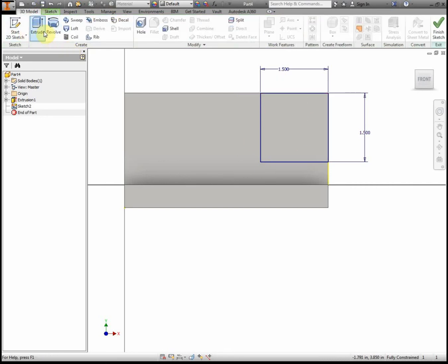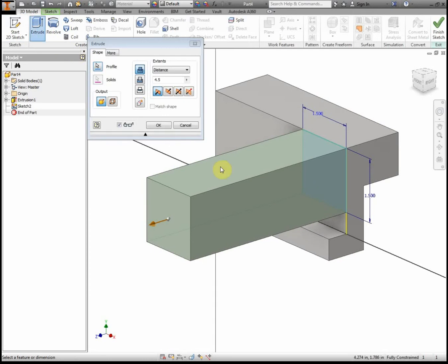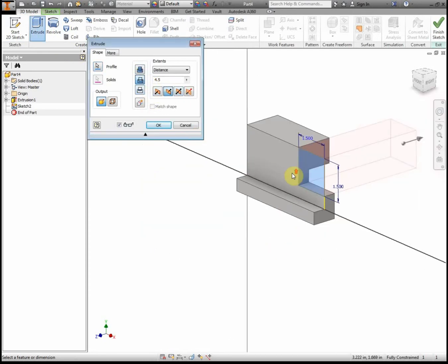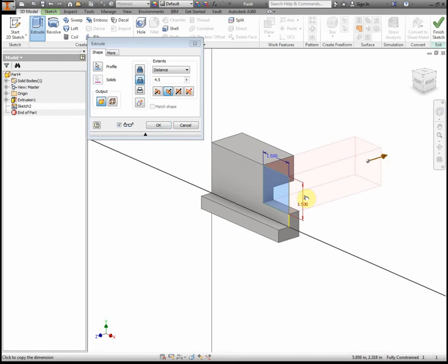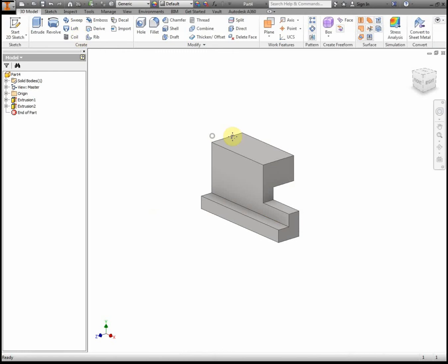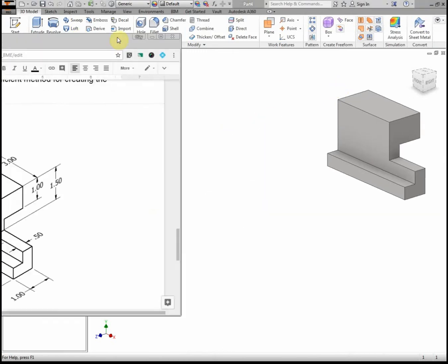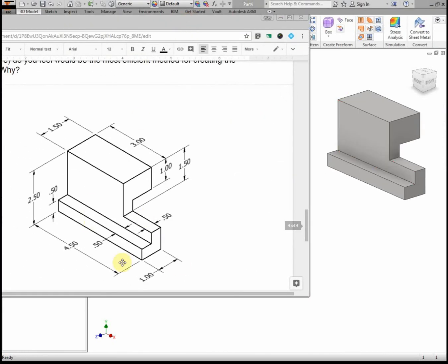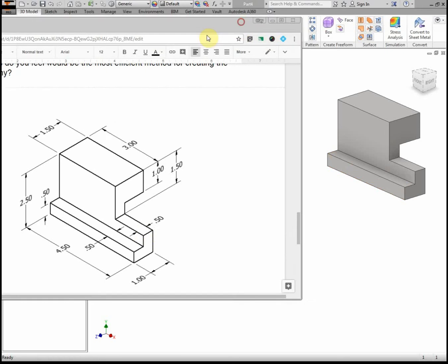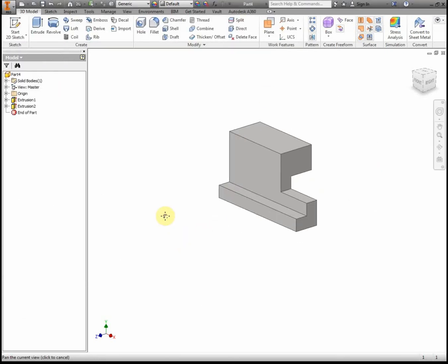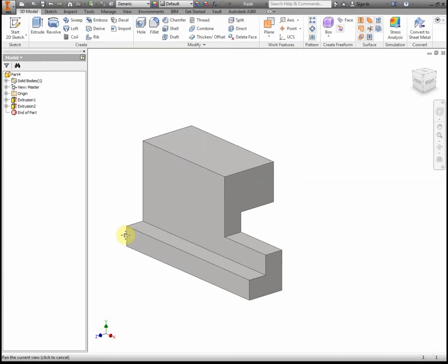Now we're going to cut. So I need to extrude that piece. Ooh, I don't want it to stick out though. I want that to be a cut. So I'm going to take it back. Notice how far that pink goes. I don't want it to go back that far. I just want it to go through all. And then hit OK. I'm going to slide this over, bring our picture in. Look at that. Perfect. Beautiful piece of art. So that's our shape.